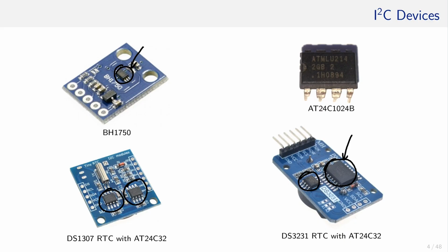In this scenario, the measurements could be communicated to another system with a larger memory. However, communications are costly in terms of power consumption. The other inexpensive alternative are EEPROMs, which come in various sizes of several megabit and are accessible via I2C.